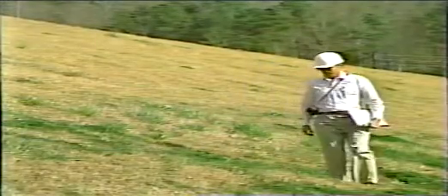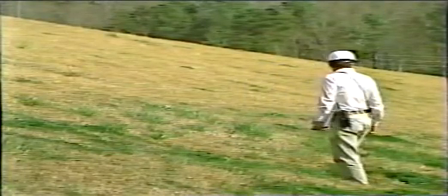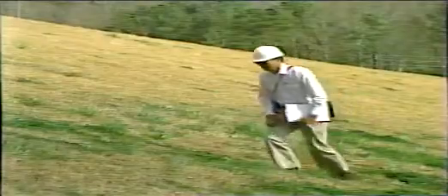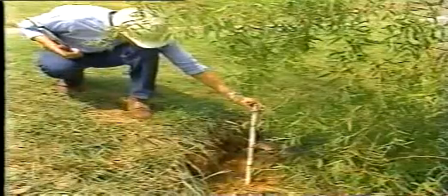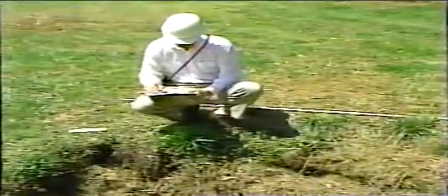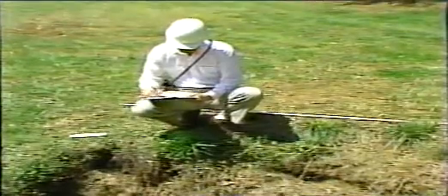Localized settlements are known as depressions. Depressions have gently sloping, bowl-shaped sides and are usually not serious. A more serious type of settlement, a sinkhole, is characterized by steep sides where the soil has sheared as it settled. Sinkholes are serious because they indicate the removal of underlying material, possibly due to piping. If you find a sinkhole, contact an engineer immediately.